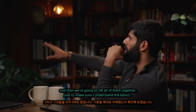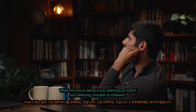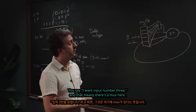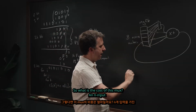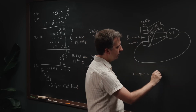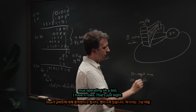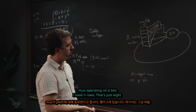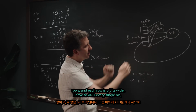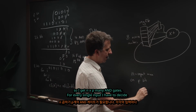Just to make sure I understand the basics, what the Mux is doing is just selecting an input. Just selecting an input. Invisible to software, you say I want input number 3, that means there's a Mux here. And what is the cost of this Mux? So an N-input Mux operating on P bits: I have N rows, that's these 8 rows, and each row is P bits wide. I have to AND every single bit. So I get N times P many AND gates.